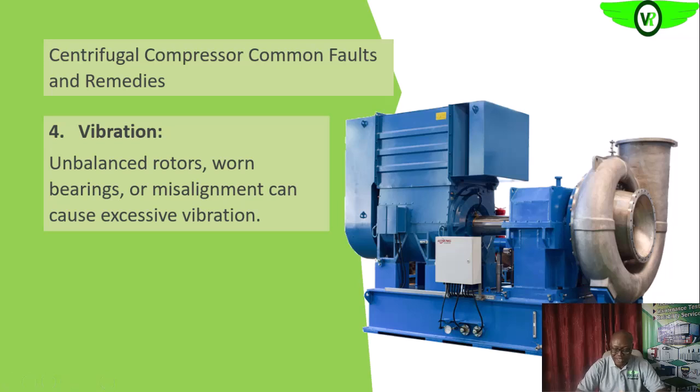And then misalignment between the gearbox and the electric motor. The coupling, if it's misaligned, that can increase the vibration, and even between the compressor and the gearbox, if it is not properly aligned, all of those can increase vibration.